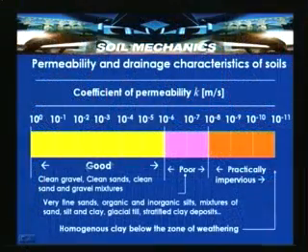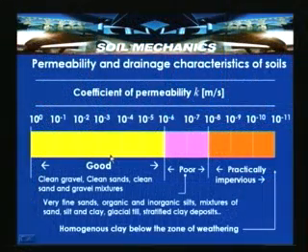So, here from the drainage point of view, many times we are required to select a particular material for performing drainage. For example, under parking lots or under footpaths or under market yard pavement paths and below the subgrade, road subgrade. So, here the drainage is very important in such locations. Good drainage conditions for a soil can prevail if the permeability is in the range of 10 to the power of 0 to 10 to the power of minus 6 meter per second.